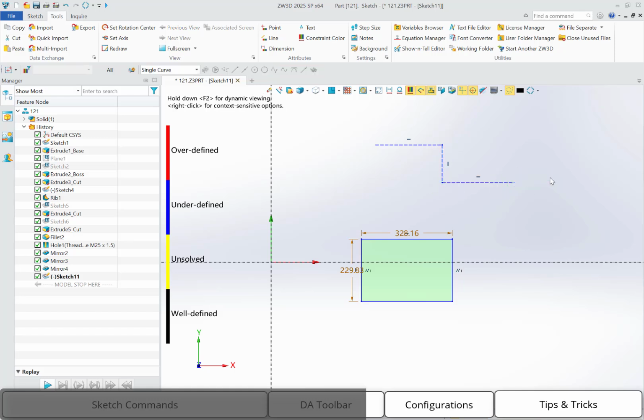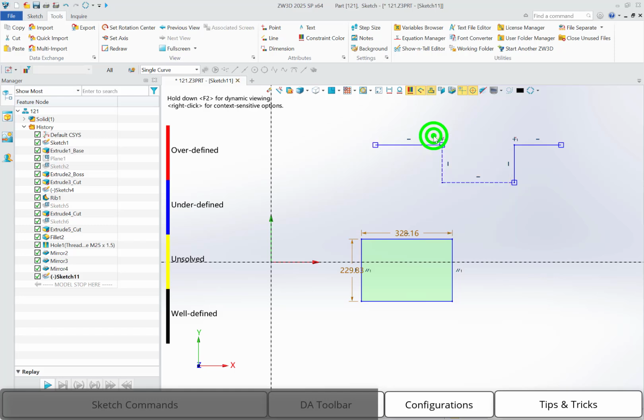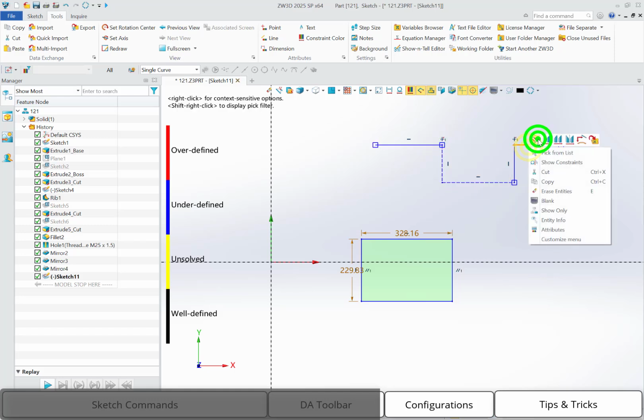And actually for me, I already made a shortcut key. You can see it's switch off, switch on, switch off. And then I can start with the solid lines. And after that, you can also turn them the opposite way. For example, for a construction line, you can use the right-click menu to turn it into a solid line. For a solid line, you can do the opposite.